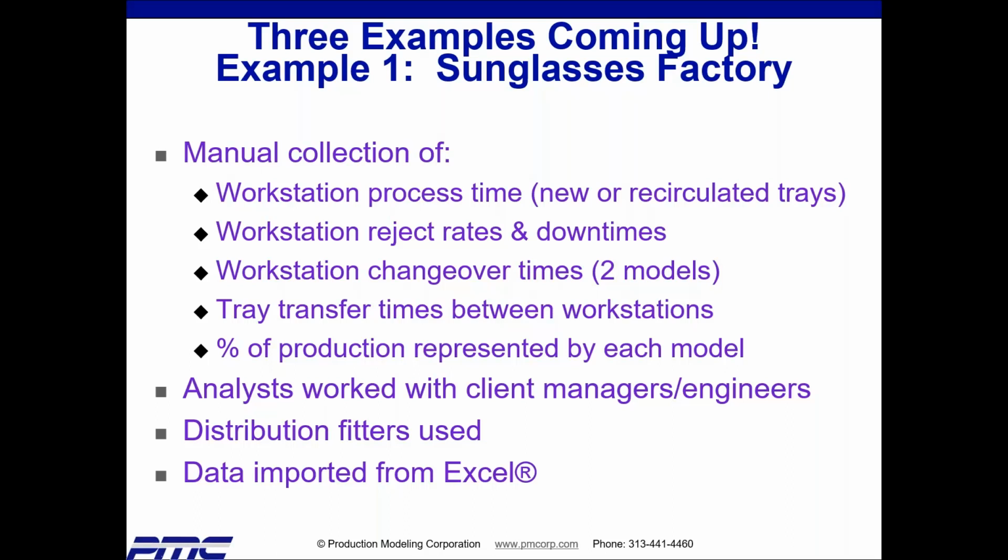Reject rates. We've already talked about downtimes, closely related, but not at all the same. The workstation, machine, whatever it was, it didn't break down, but it introduced a defect, and then we have to either throw that one away or maybe send it to a special place and we can repair it and put it back in the line. And all the data pertinent to that needs to be collected, analyzed, and put in the model. And the very first one is the most obvious one. So that's what you'd call the cycle times.